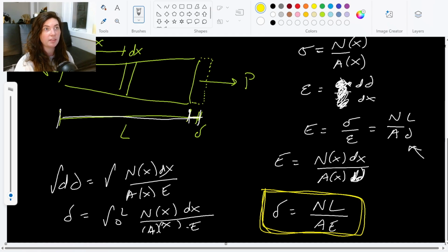It lets us do even more things with our stress and strain calculations, relating them to the modulus of elasticity using this relationship. The integral one is really, really helpful too, especially if you have changing loads and changing areas that we couldn't really deal with very well before. Now we have this handy integral to deal with that, right?